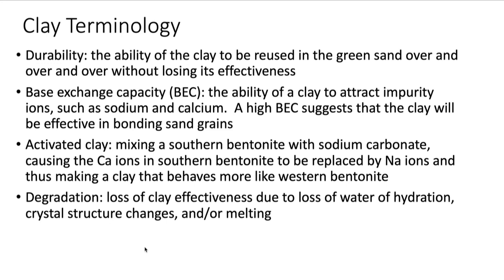Clay needs to be activated. Mixing it with sodium carbonate can cause the calcium ions to be replaced by sodium ions, thus making it behave more like Western bentonite. What I meant by activated is that it has to be activated if you want to make a Western bentonite more like Southern, or Southern bentonite more like Western. So they can try activating it with one or the other. Okay, it's still not as good as actually mixing the two together.